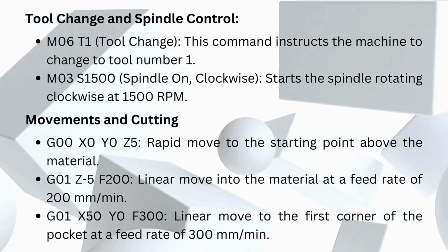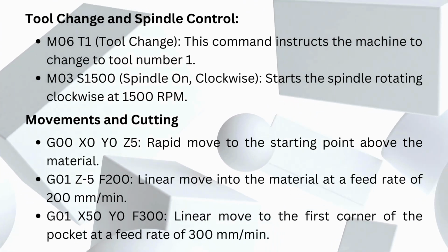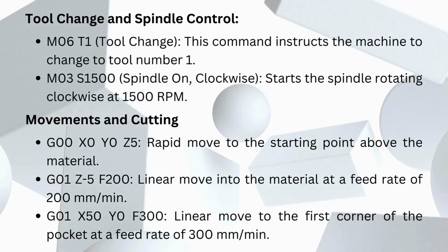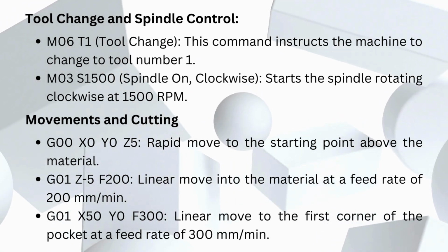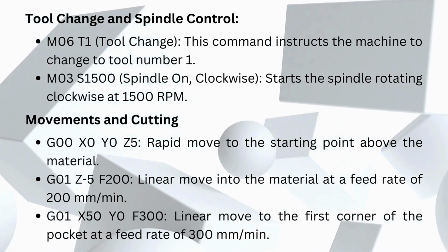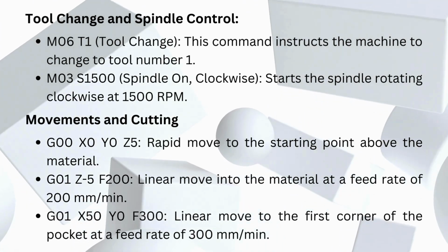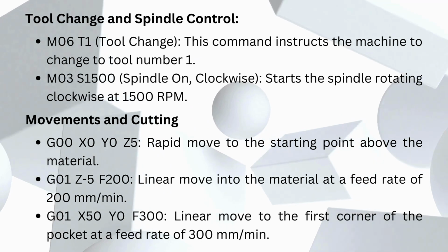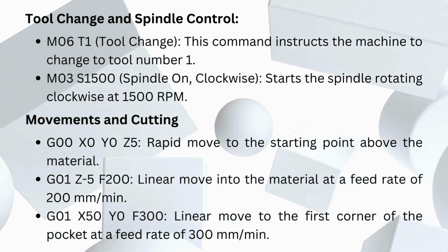Movements and cutting. G00X0Y0Z5, rapid move to the starting point above the material. G01Z5F200, linear move into the material at a feed rate of 200 millimeters per minute.